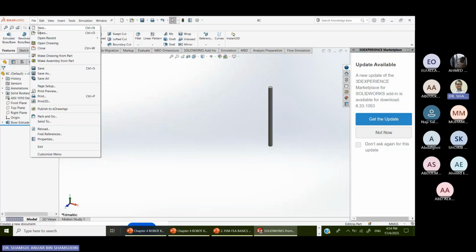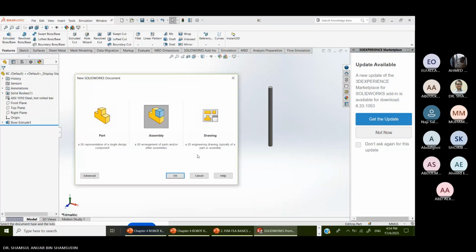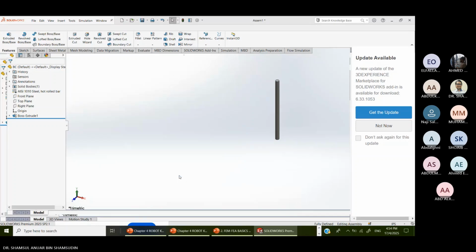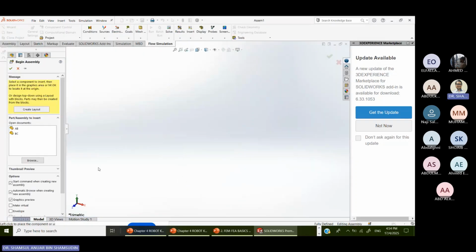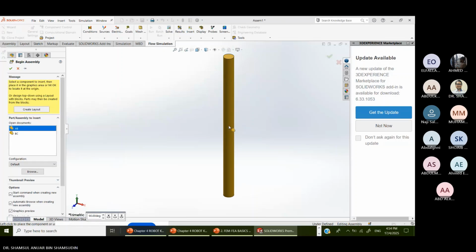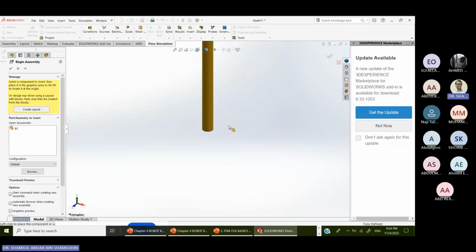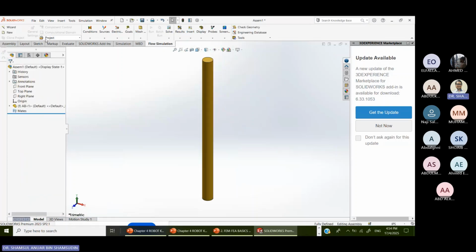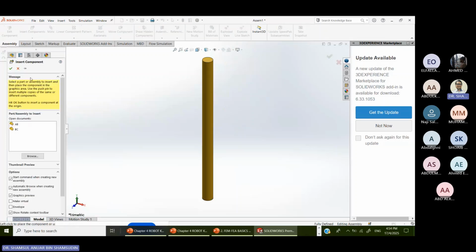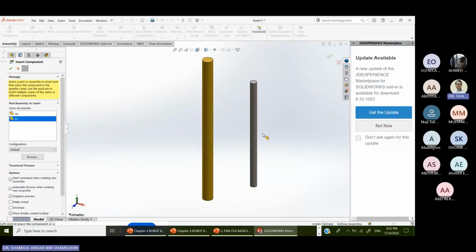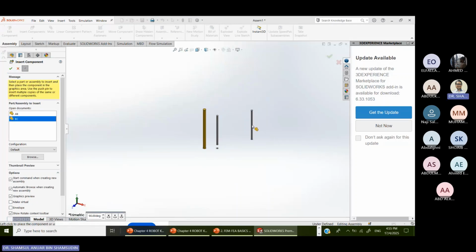So next, I want to create a new one where I combine, assemble. So this is assembly. So I want to create using AB first. So create AB. Hit enter. Don't put it anywhere. Hit enter. And then assembly again. Insert component. Keep visible. Want to click BC. Put it over here. Okay, and then escape.